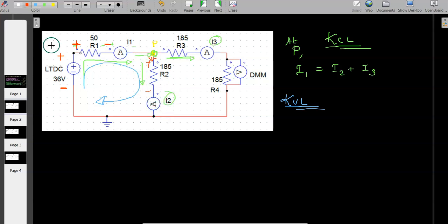Then what we get is the potential rise. The potential rises from this low tension DC, direct current, source. So this 36 volt is a potential rise. If I consider some current flowing through this particular resistance, the drop across R1 is VR1 and the drop across R2 is VR2. Then this 36 will be equal to the potential drops in this loop, that is VR1 plus VR2.